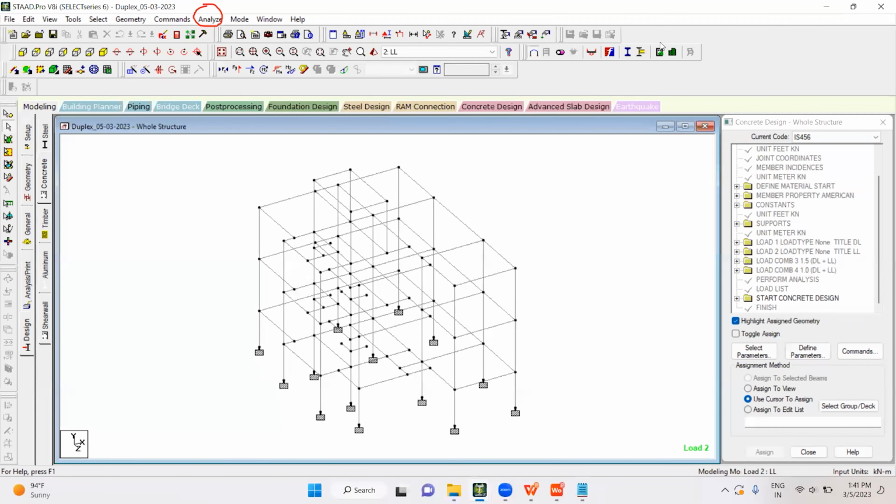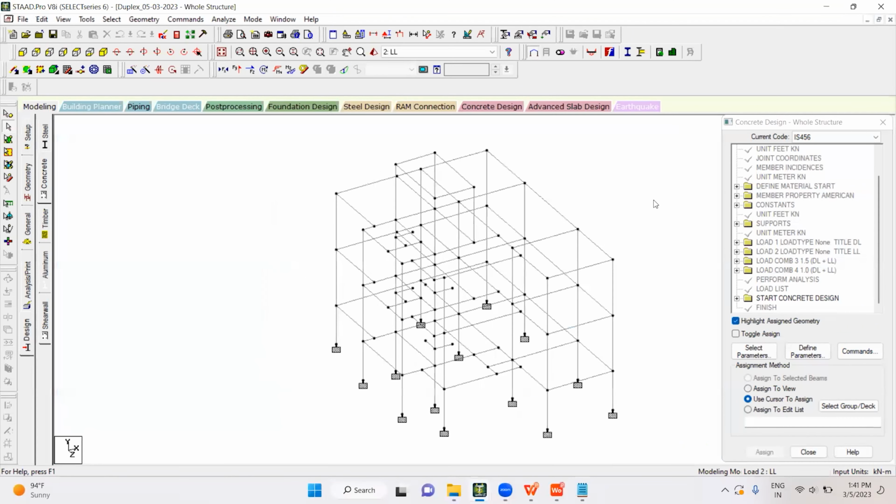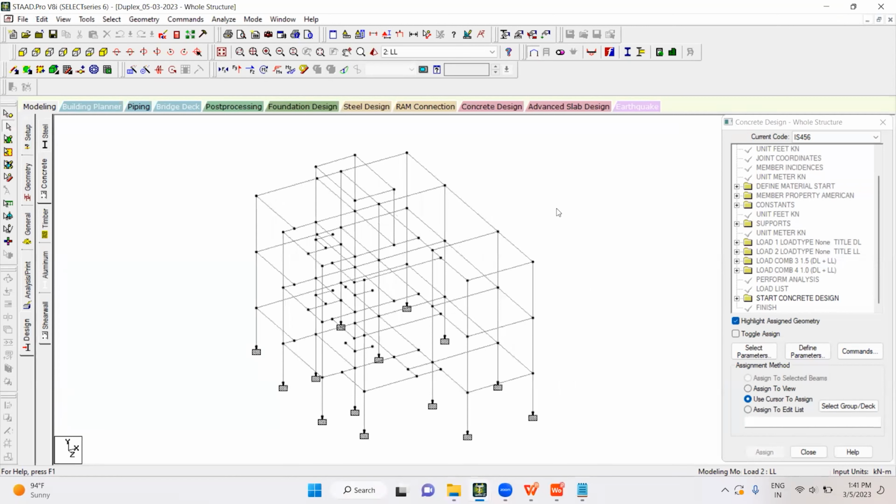So the conclusion of this discussion is that our entire structure, the columns and beams, has passed because we used thumb rules. We are suggested to use different column sizes for different numbers of floors. If it is G+2, try 230 by 375, and members will pass. If it is beyond G+2 floors up to G+4 floors, you change to a different column size.